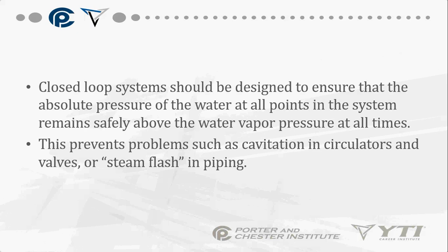Because we do not want to feed cold city water, which could be like 40 degrees, into a warm boiler. That can be catastrophic. That can actually damage your valves. It could damage your cast iron. It could crack a boiler. It could make a boiler literally explode, guys.